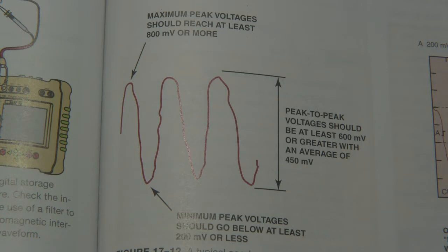Its image, its voltage is not clean enough or hitting maximum ranges. And so the enabling criteria for the monitor of individual oxygen sensors is going to set up parameters for minimum cycles, for example. You know, how high a voltage it must go to.